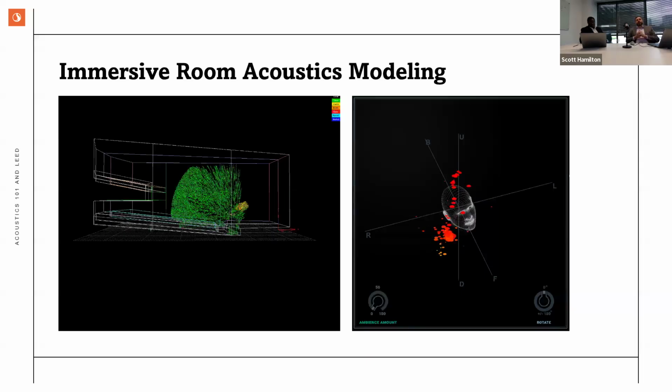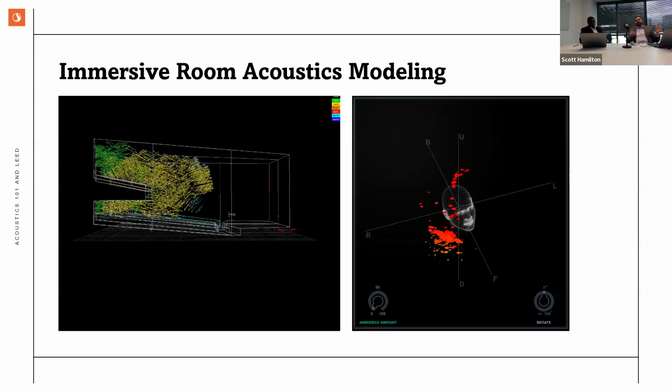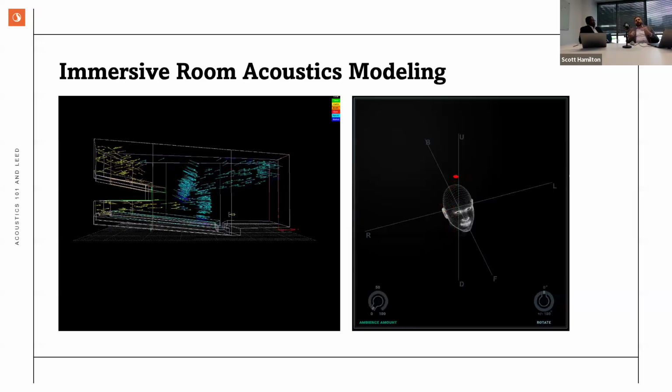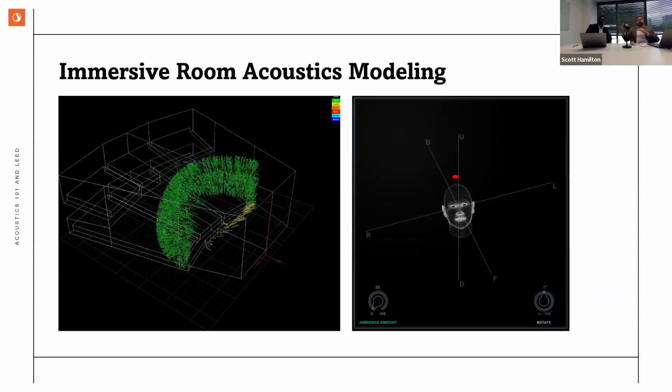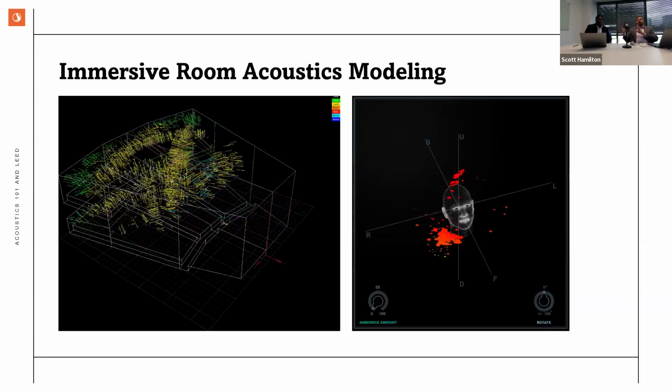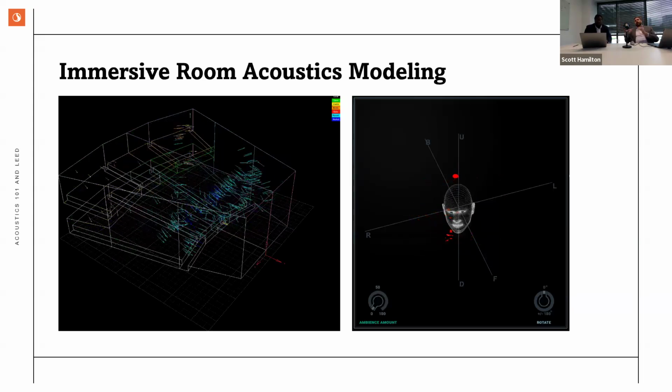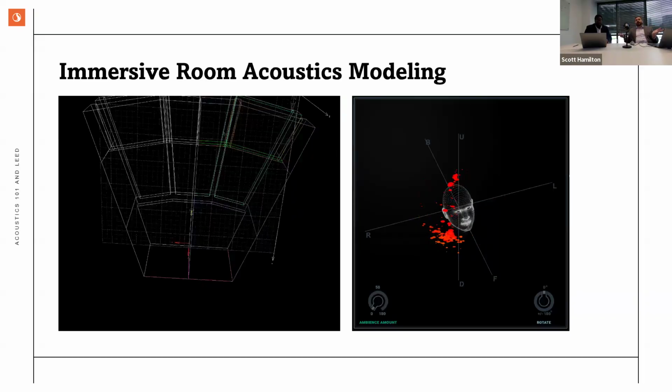And we try to provide finishes at the right spot, manage those early reflections, because when a late reflection comes to the stage, it's bad. At the right time, it's great for a musician or a speaker to hear something, but if it comes back too late, it's a slapback echo and it can actually throw the musician off beat.